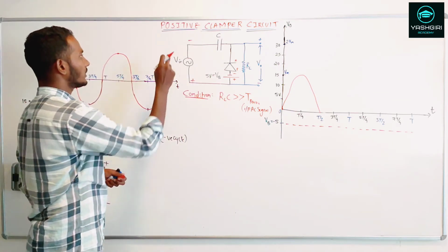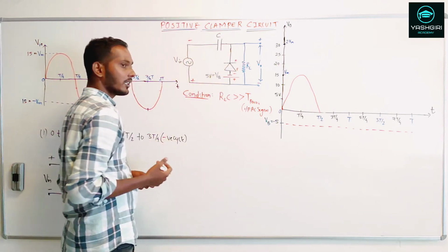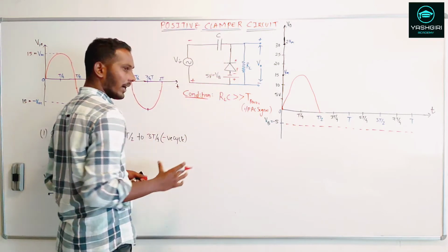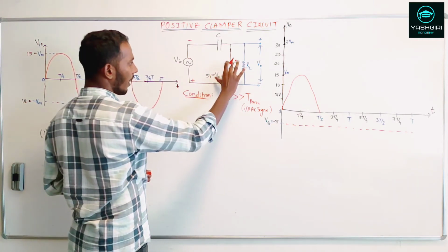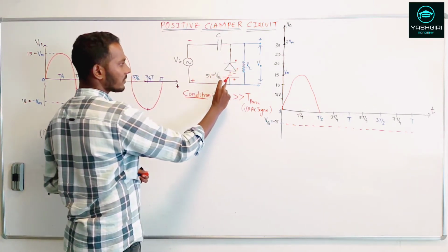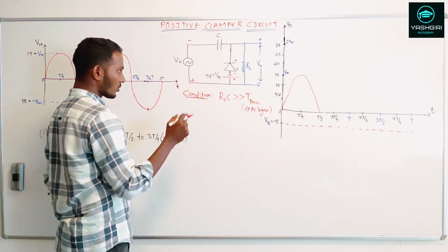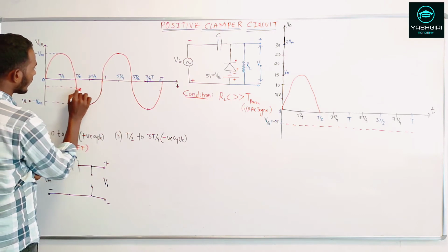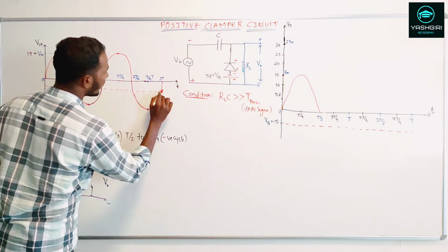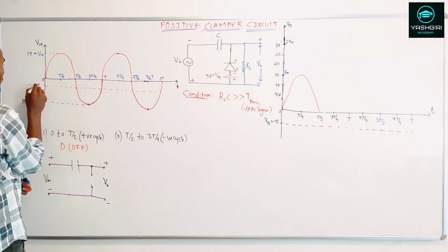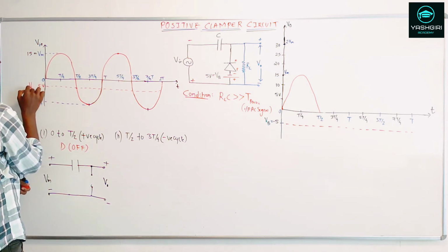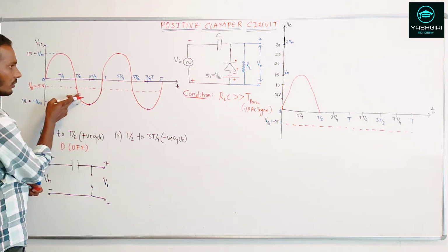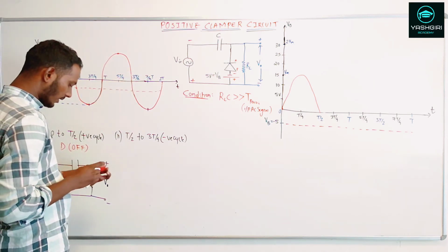Now if you see the connections, minus is connected to the N side, that means there are chances of making this diode forward biased. But again, the barrier potential has increased because of this biasing voltage VB. So we need to overcome that barrier. On the negative side, let me show the 5 volt battery. Let's take the biasing voltage VB equal to 5 volts. Once V input crosses this 5 volts, the diode will start conducting.